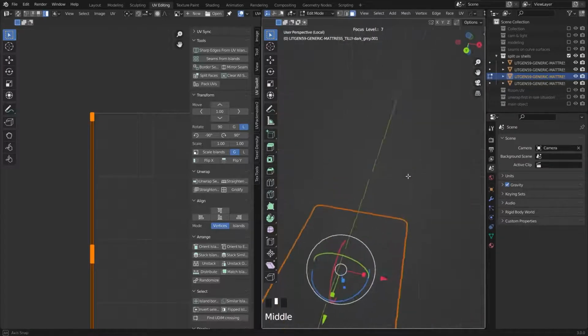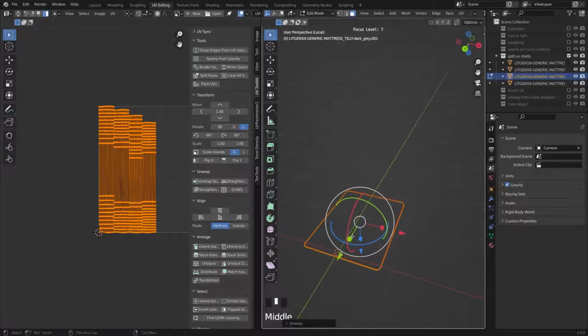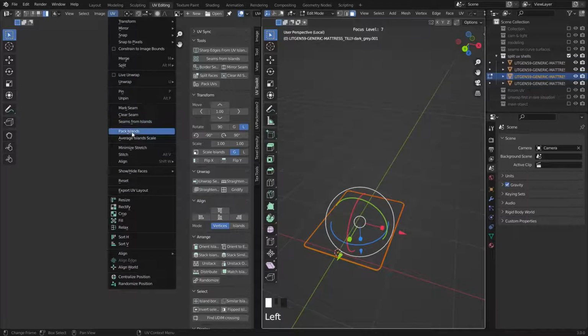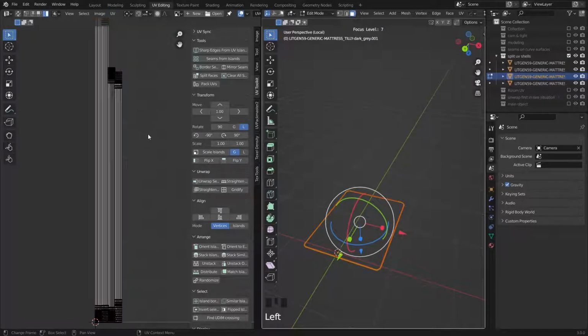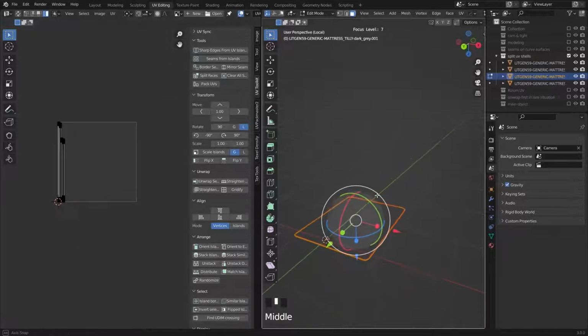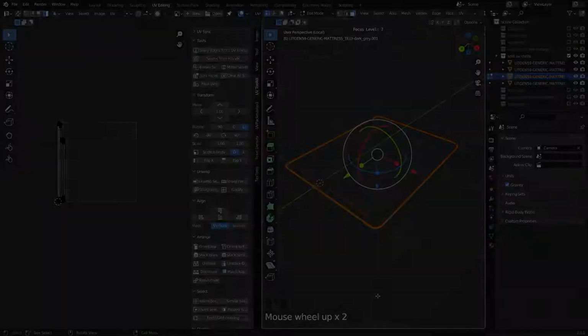So if now I hit U and unwrap, you can see I split it into 4 UV shells and I straighten all of them, and also I want to average and pack it. You can see now I can use more of my unique texture space. Okay, so you should do it if you have this kind of long object.